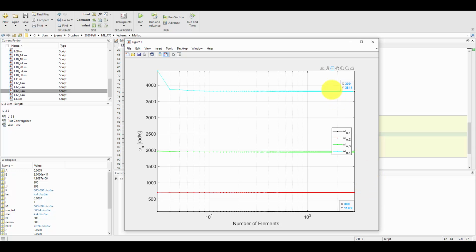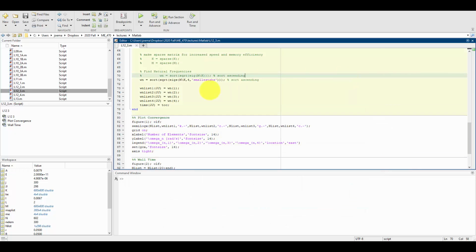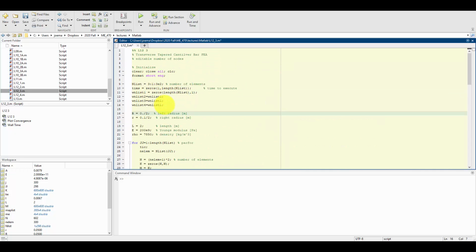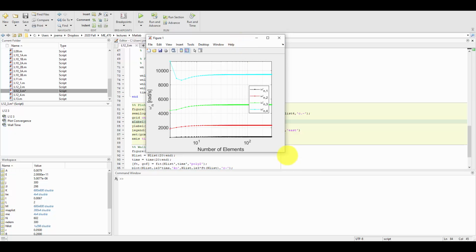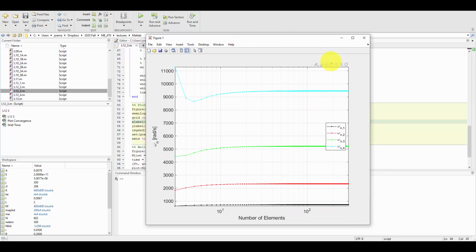So we're getting 3 different results this way: with the taper, with everything as the small diameter, and everything as the large diameter. So let's pull it all together to make an assessment of, can we trust the results we got when we put the taper in for the FEA? And let me just rerun that original one more time here. So this is with the taper and with the FEA. These are the results we're trying to validate here to see, do they seem like they are any good? Again, highest natural frequency of the 4, 9460, and the lowest, the first natural frequency, at 735.